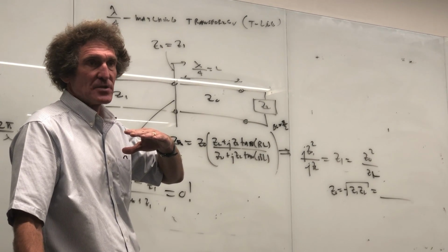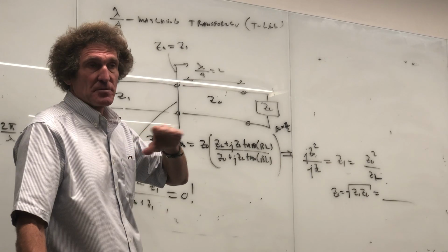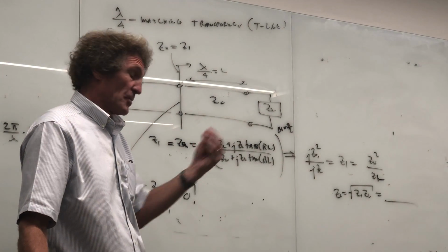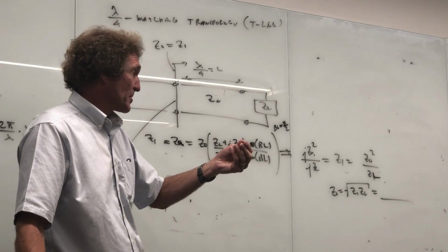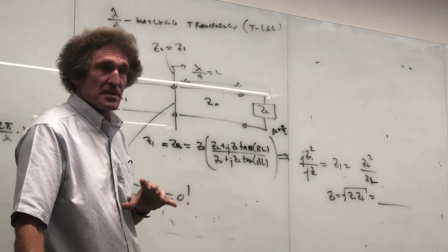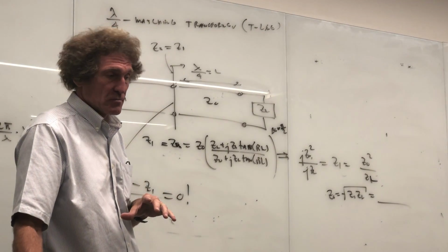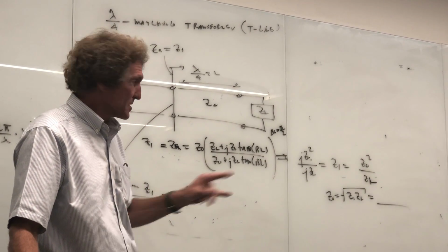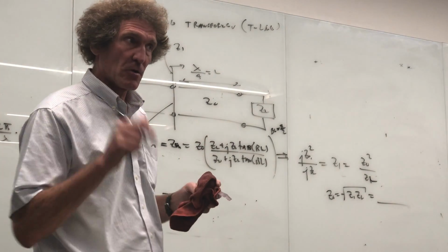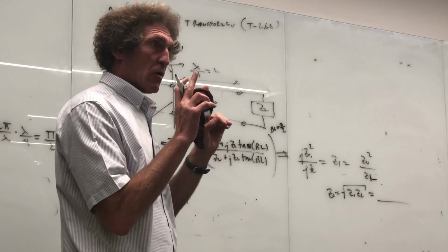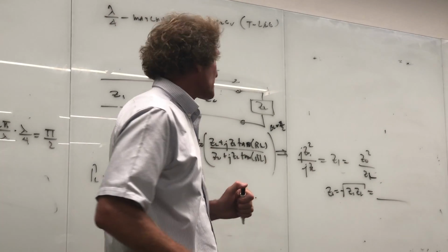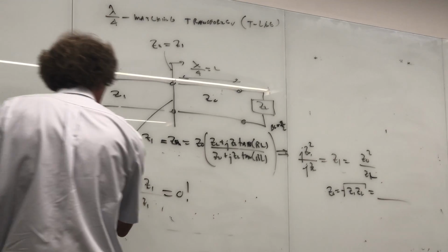You basically create structures so that the transmission lines on those structures will have an impedance equal to the square root of your load impedance times the impedance you're coming from, and you can easily design transmission lines to meet this goal. So you want the characteristic impedance to be that. This is a trick. It only works at one frequency though, remember, over a small band. It's frequency dependent. Now, for the Smith chart, I wanted to show you that one.